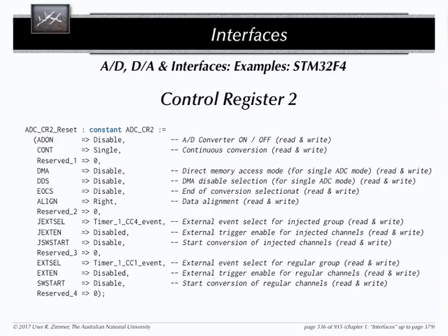Now if you have pulse width modulation, you don't have that. And you have the advantage that you always operate on maximum torque, because you have maximum voltage always applied, if only for a short amount of time. But this maximum voltage translates into maximum torque and is independent of speed.